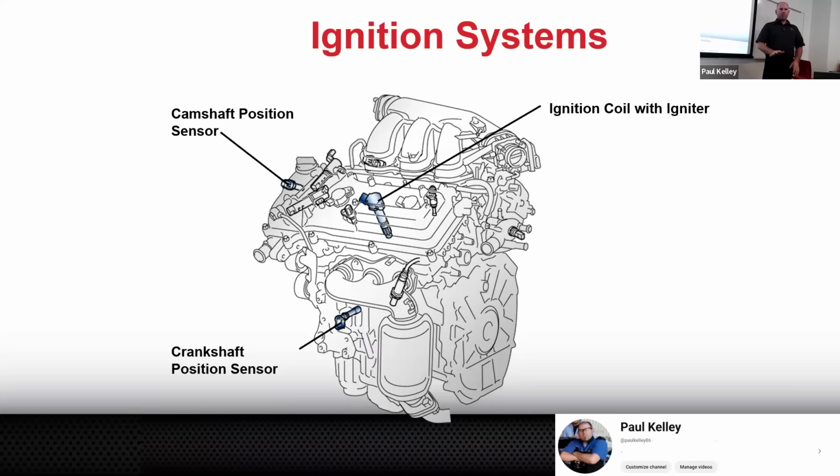But the matter of fact is, primary ignition code, we're talking small wires right here. Primary ignition code will cause a misfire. It's just the way it is. So let's just say you wanted to diagnose the primary ignition side. That's when we need to get into that ASE electrical module we did before. It's probably going to be like 12 volts, and then maybe the ground is going to be controlled by the ECM. It's going to be pulsed or whatever.